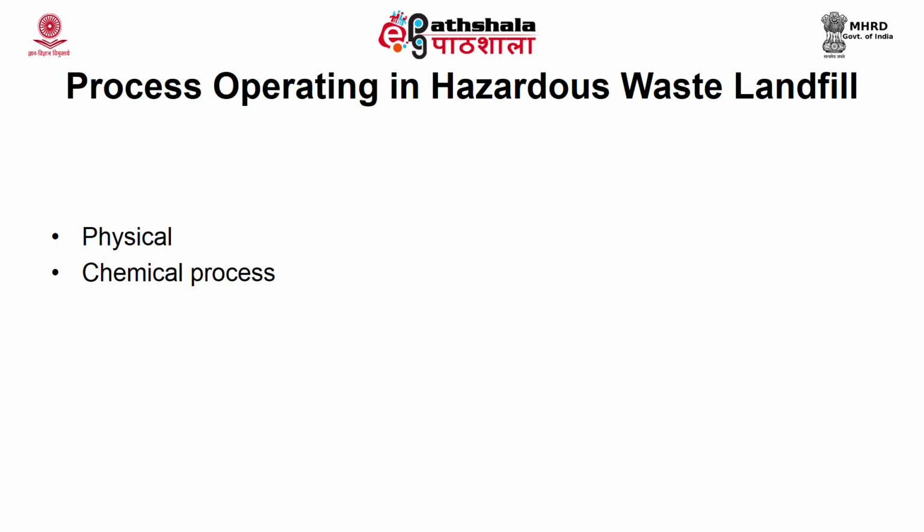So, as I told you earlier, inside a hazardous waste landfill the majority of chemical reactions take place, like there will be complexation of species, there will be precipitation, you can find salts getting precipitated, and there will be an ion exchange process where the cations and anions get exchanged.